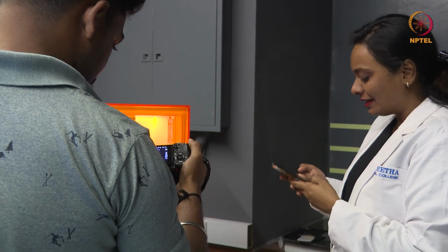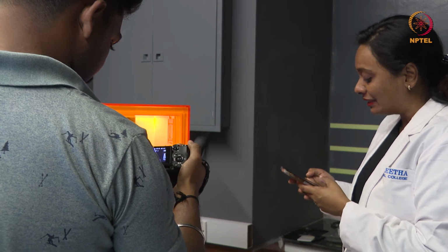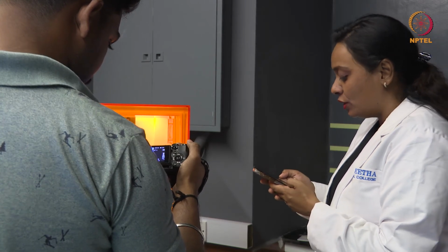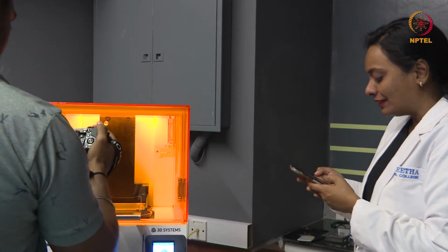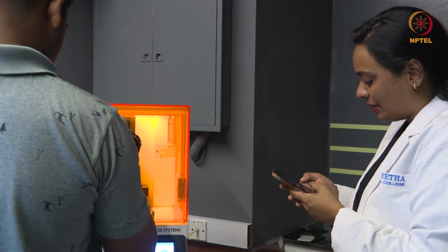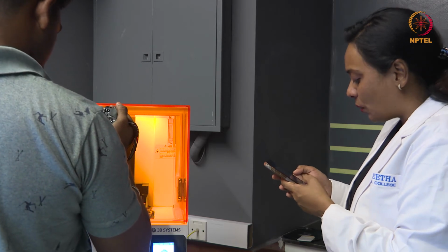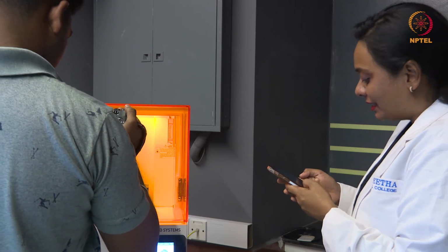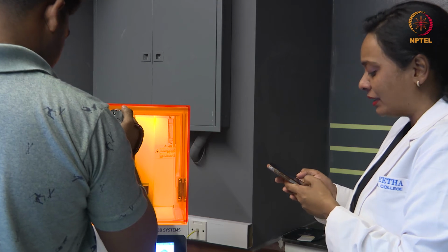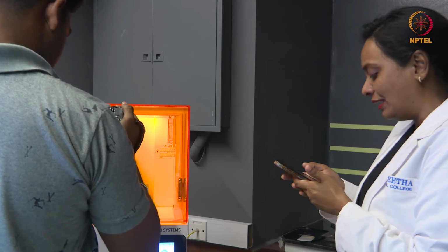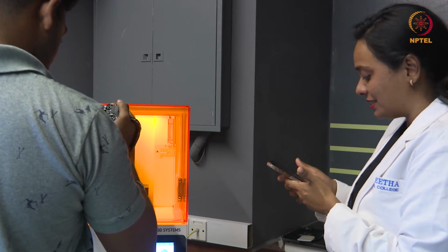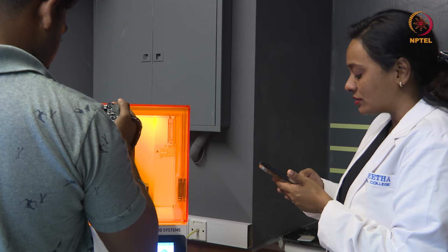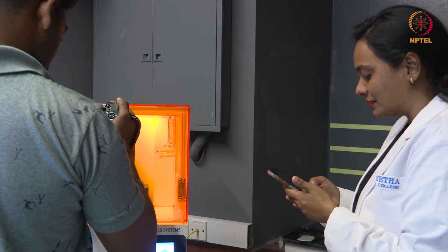These are mirror-like components used for navigating the laser beam of an SLA printer to the bottom of the tank. With the help of G-code, galvanometers navigate the laser beam in a path which represents one layer of a certain part. The laser then cures the resin, making a solid layer of the part. When one layer is complete, the build platform moves up, like you can see here, one layer in height, and the process is repeated until the part is complete.